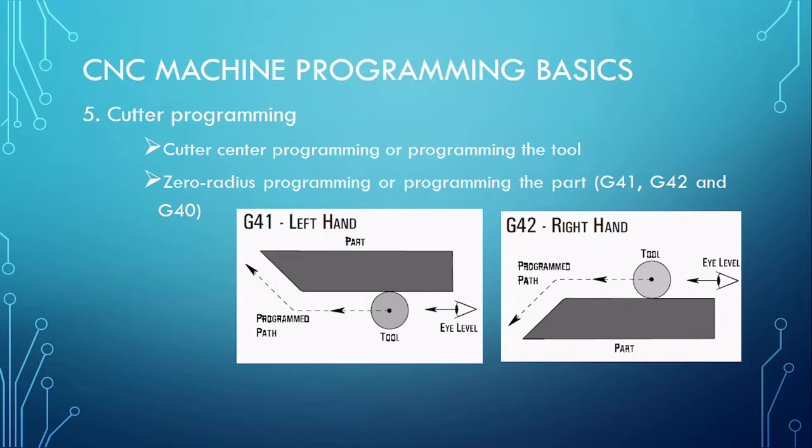However, this is only applicable where the operation on the workpiece will be achieved by just one cutter. Where a lot of cutters will be used on a workpiece before the final profile is obtained, adding the radius of every cutter to the profile will be very difficult.